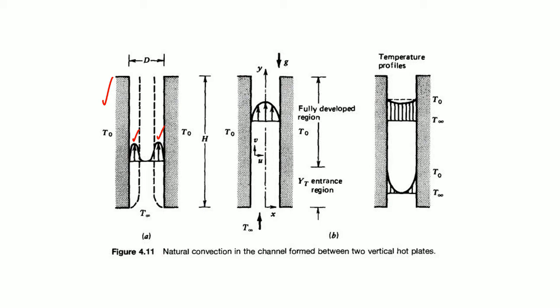Let us look at scenario 2, when the distance between these walls is very close. That means these two velocities will now start to crosstalk. By crosstalking we essentially mean that they will merge, and you get a velocity profile very similar to what you would normally expect in a duct in the forced convection paradigm. So, the flow will be like that. You will not be able to distinguish the two wall jets; they are basically crosstalking with each other.